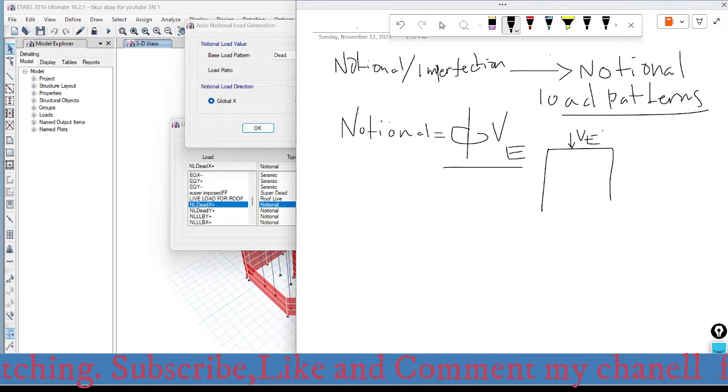This story force has to be converted into the equivalent lateral force, just like this. This force is the equivalent horizontal force, which will account for the imperfection problem of this structure at this level.